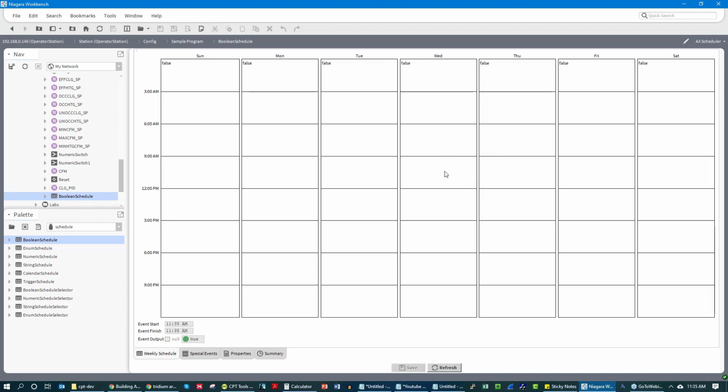Now, my personal philosophy on schedules is that you should schedule equipment individually based on occupant patterns. So if you have 3 air handlers that serve customer A and customer A works certain hours, then those air handlers would be tied to customer A. And if you have customer B, then those air handlers that serve customer B would be tied to customer B, and then your atrium and things like that would be tied to a common schedule.